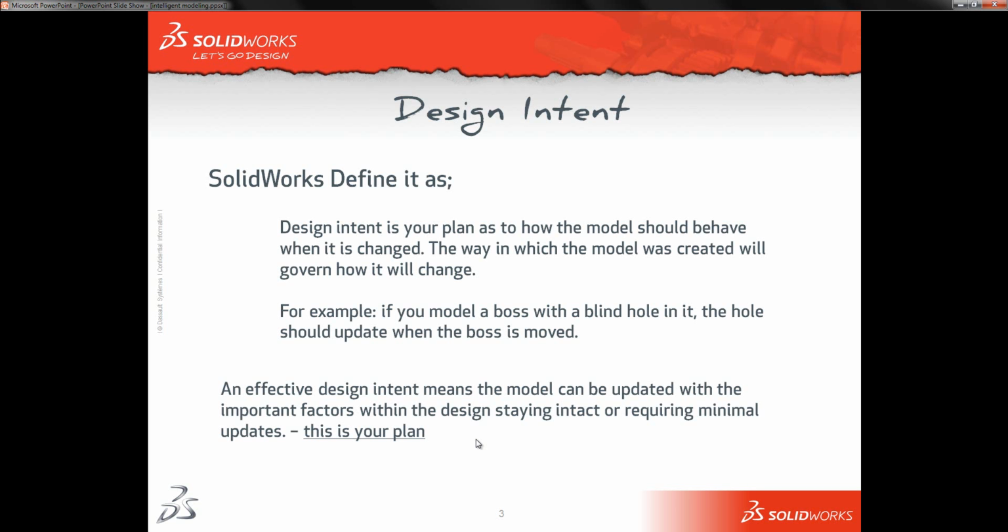One of the first places design intent starts within a design, and one of the first places we can build up intelligence, is within the sketch of that first feature or first few features within the model. By building up sketches effectively within SolidWorks and adding sketch relations in a good way, we can build up a lot of design intent from those initial stages.